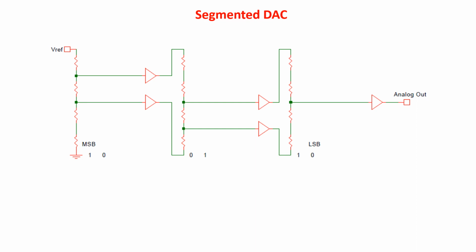If Vref is 8 volts, the first segment selects the voltages between 4 volts and 6 volts. In the second segment we select the second resistor, so the voltages between 4.5 volts and 5 volts. The third segment selects the third node, so 4.75 volts, which is also the output value.